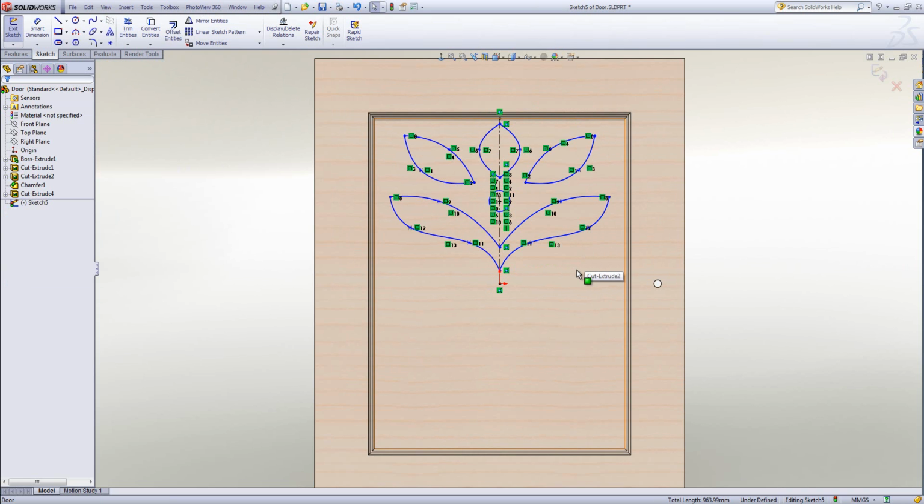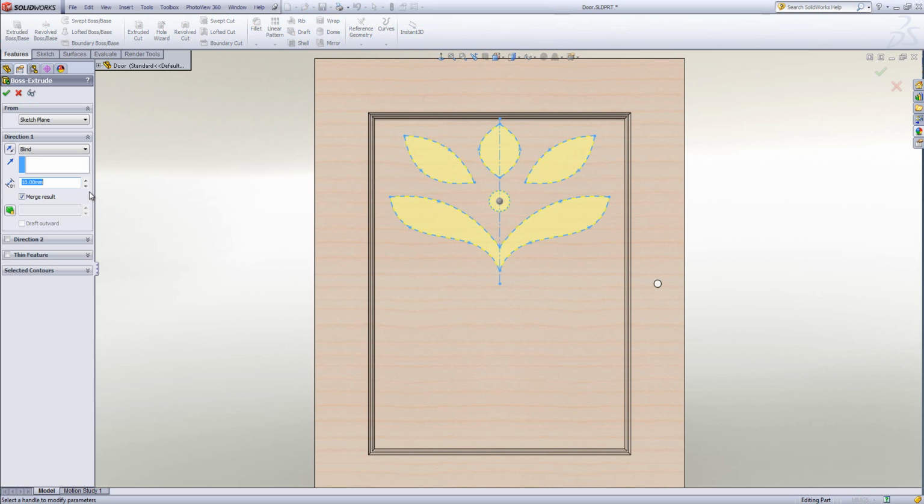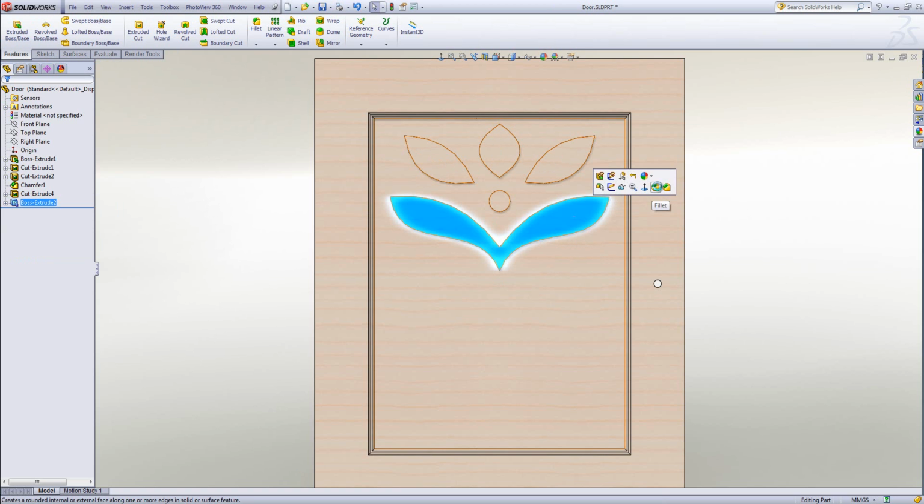Now ordinarily, when you're constructing these items, you'd build in some extra parts in the design so that when it comes to mirroring it over, you've got dimensions and everything like that to hold it in place. In this design, I'm not going to bother dimensioning up too much, just for the speed of creation. So having created the sketch, I'm now going to create an extrude from it. The extrude is just going to be a small extrude, just by 2 mil. And I'll finish it off just with some fillets.